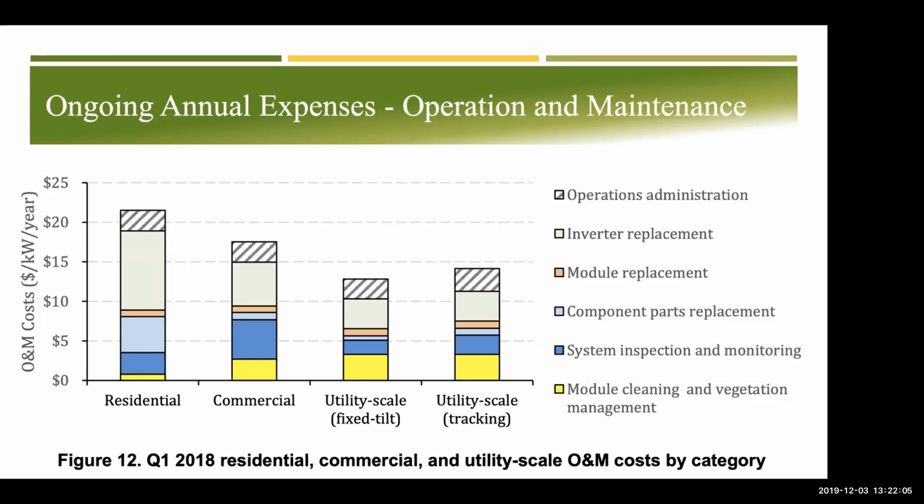A general guide that we use for O&M so that it shows up in a cash flow table is, it's been anywhere from $20 to $15 per kW annually. So it's based on the nameplate size of the system. We'll just assign a value. I tend to use $15. We can get really fancy with this, as John and I will show you next week, and actually do lower values and have escalation above and beyond inflation that's allocated towards O&M costs. So we can get pretty detailed and tricky with how we handle O&M with our modeling,